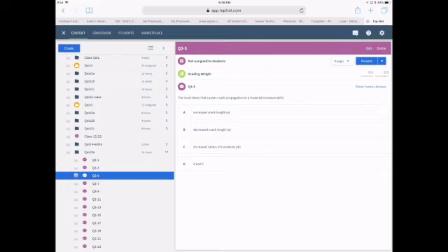Okay, so hopefully you answered A. Crack length is in the numerator of the equation. Therefore, if I increase that, I increase the localized stress. Rho sub t is in the denominator, and it will counteract increases in length, or A. So that won't help, A and C. And then obviously decreasing length, A, will not. It'll decrease the stress. If you decrease the radius of curvature, which is in the denominator, that would definitely increase it.